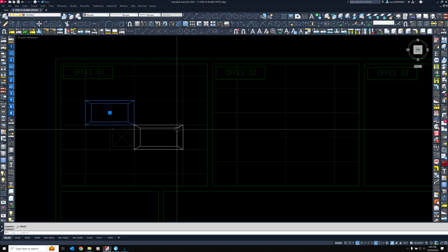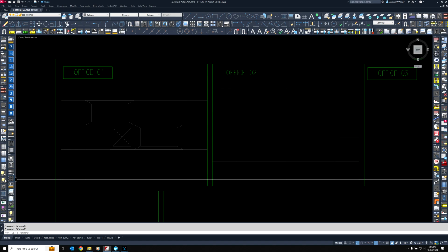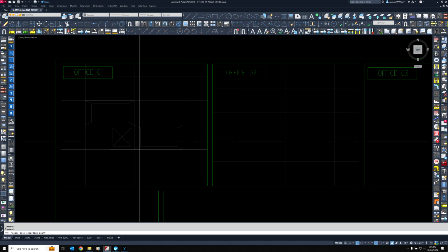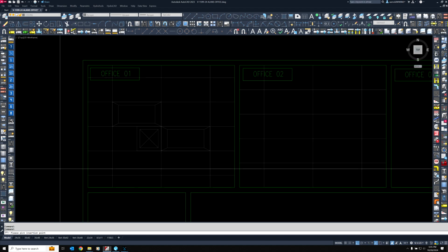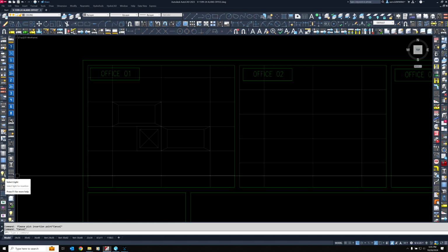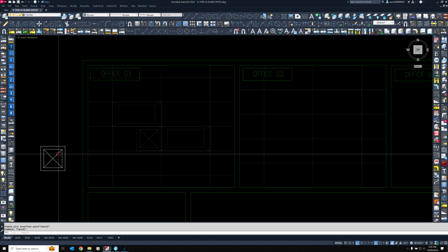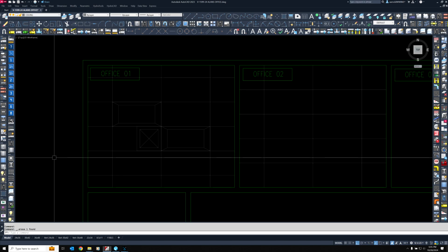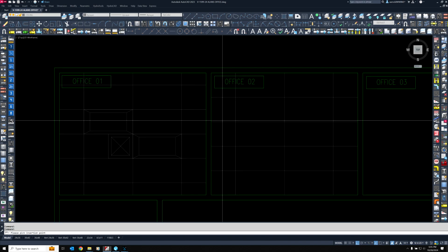Let's use that insert snap for these light fixtures. And if we come down here, insert light, pick insertion point. What it should do is remember the last thing we put in. So we're going to test this. This is how we pick the light from the start. This one says insert, and it can only insert what it's been told. So insert, left click, and it remembered the last thing you used. So keep that in mind. That's how many tools work. We're going to insert the diffuser first, I suppose. Doesn't hurt.